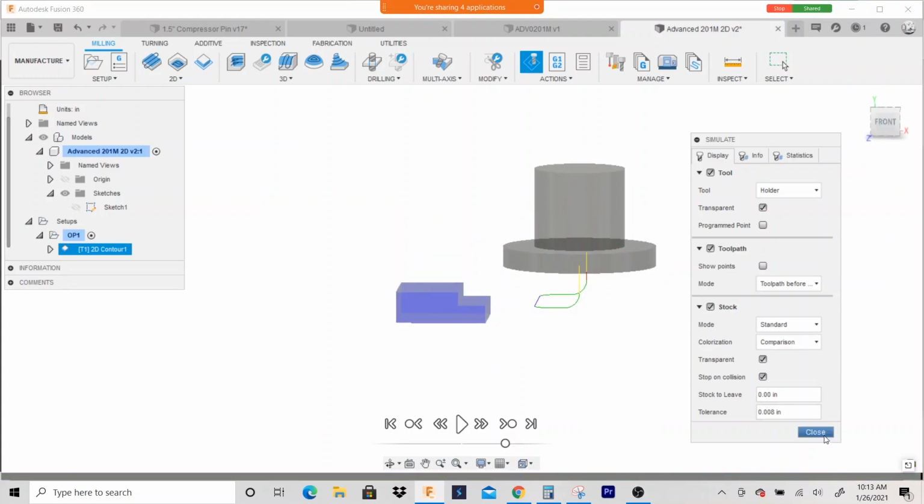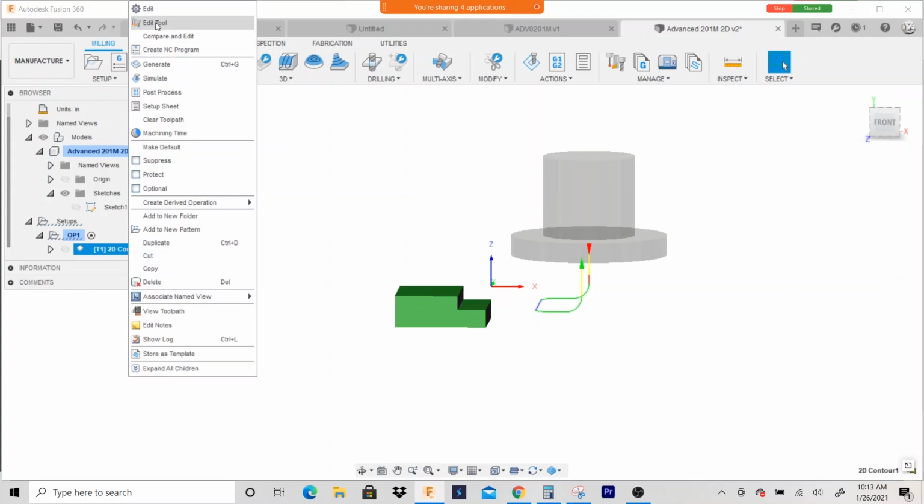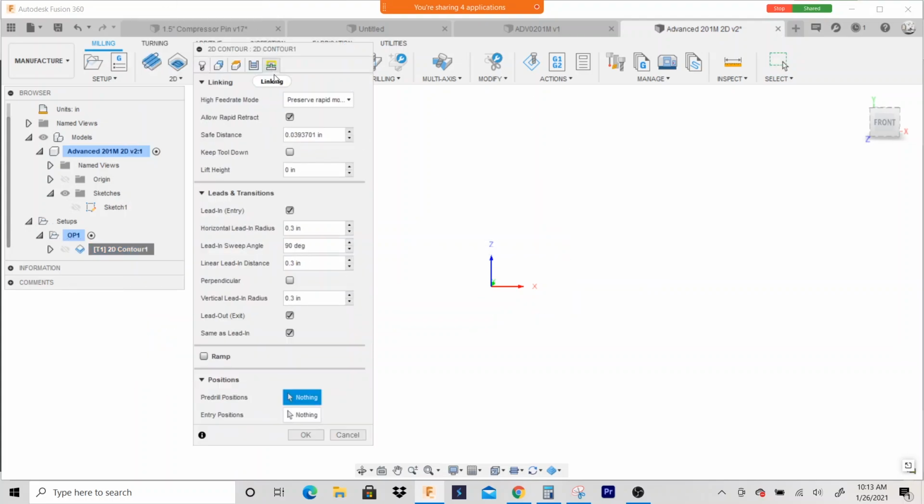But as a machinist, a lot of times you're gonna be at the machine editing code, and in that case, it's good to have 0-degree lead-ins. Because if you're a good programmer, there's a good chance you're not going to be writing the programs and running the parts, unless you work at a small shop.